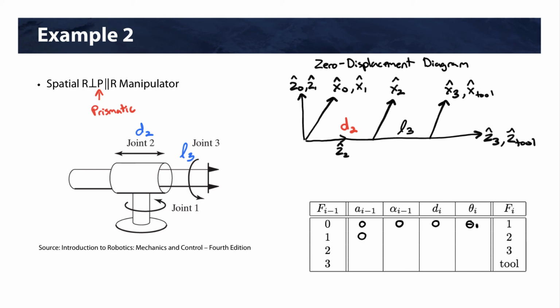All right, now we need to determine the direction of it. So to do that, you stick your thumb along the positive X1 axis. All right, this finger up is your Z1 and we're rotating. So we're curling our fingers around our thumb to get to Z2. So we know that's a positive 90-degree rotation. All right, and we're actually going to write it in terms of radians. So that's going to be pi over 2.